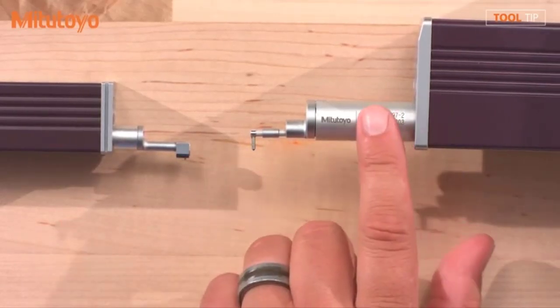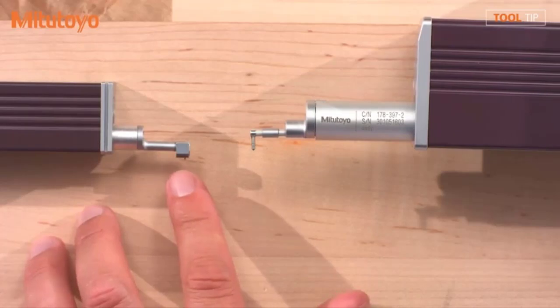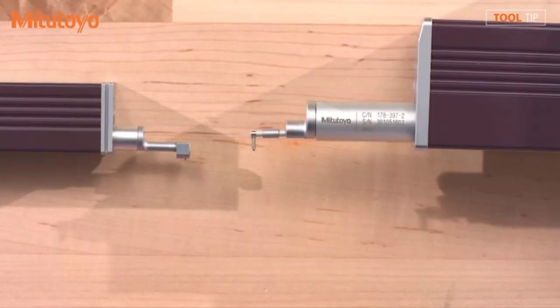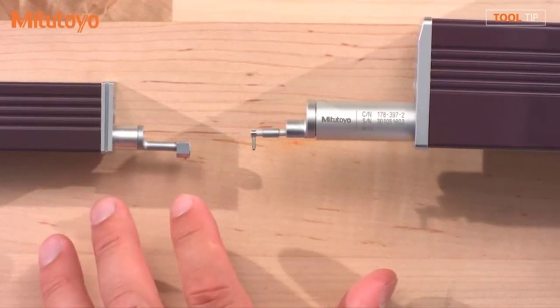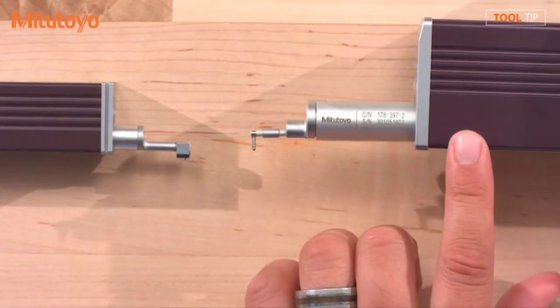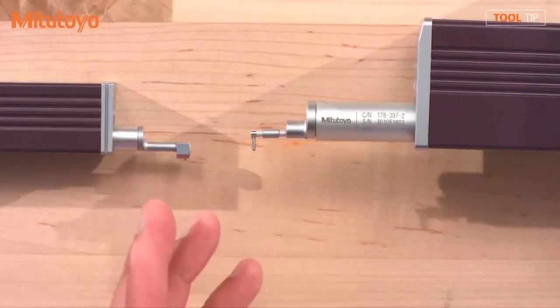Now, this is a skidless system. The skidded system is very similar, except you'll notice that the stylus and the detector are all one piece here. I still have the stylus protruding out from the detector, but around it is a housing, and that housing is what we refer to as the skid. So what's the purpose of the skid? The skid acts as a mechanical datum for the surface you're measuring. On a skidless system, that datum is actually inside the drive unit. Most entry-level systems are the skidded unit with the housing around the stylus. So Drew, now that I understand the physical differences between the devices, what are some differences in application?